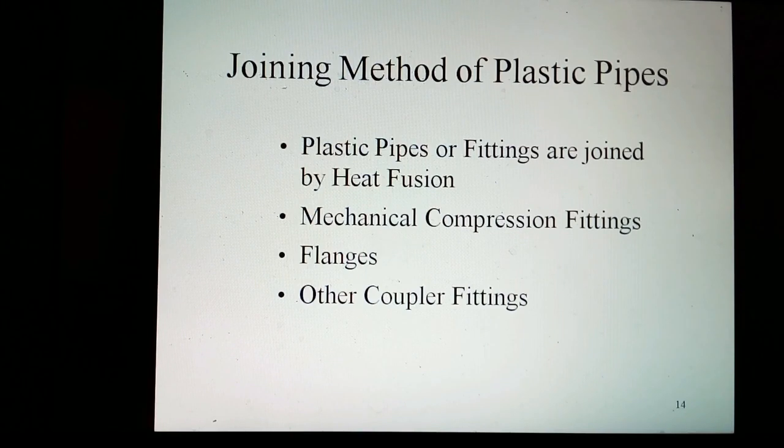All individuals involved in joining pipe systems, whether they be using the typical heat fusion methods or employing mechanical connections, should be fully trained and qualified in accordance with applicable codes and standards and as recommended by the pipe or fitting manufacturer. The equipment used in the process of making heat-fused joints must be designed to operate for the selected pipe and fusion procedures. Additionally, the equipment should be well maintained and capable of operating to specification.